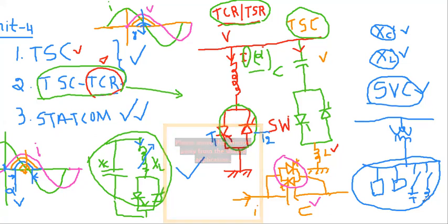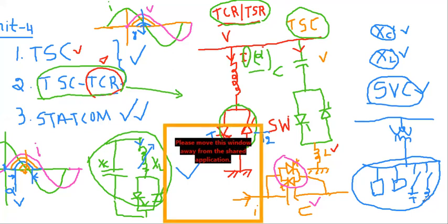the LC to that third harmonic frequency, 3 into F, and we place that LC value here, so that for that voltage or current it will act as a short circuit path, so that it is absorbed by that filter, and it won't affect the loads connected to the same transmission system. So that is the passive filter. That is also taken in this SVC.